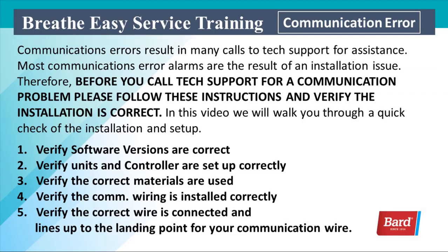Verify that the software versions are correct. Verify units and controller are set up correctly. We'll also verify the correct materials are used and the communication wiring is installed correctly. And then we'll verify that the correct wire is connected and lines up to the landing point for your communication wiring.